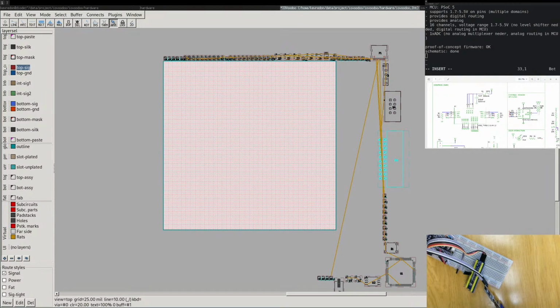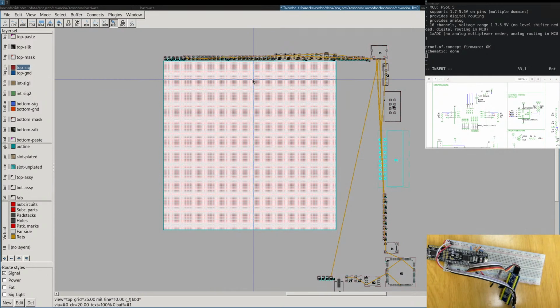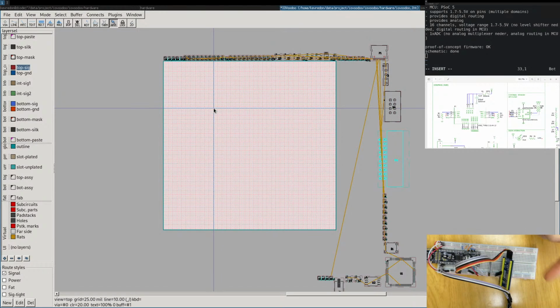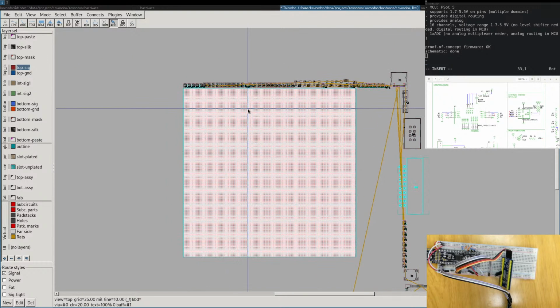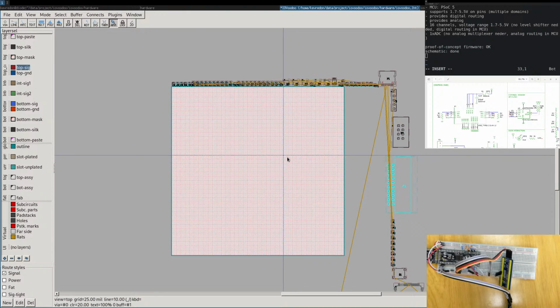And we also want to have some single-sided load because we have enough space. This is a prototype. We are really not constrained by space. But we wouldn't really care if it's one-sided or two-sided because we're soldering by hand. So the manufacturing cost of putting it 2 times in the oven isn't there because we do it by hand. First prototype. Afterwards, it's more important for the second prototype. Once this works for the second prototype, we have to pay attention to that. So we have all the components. Now we need to change the routes.